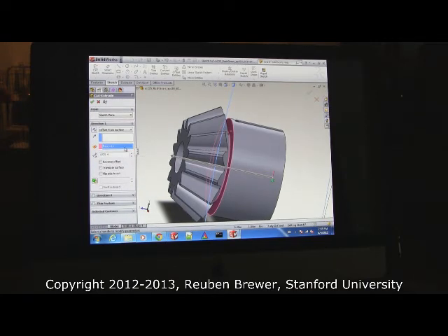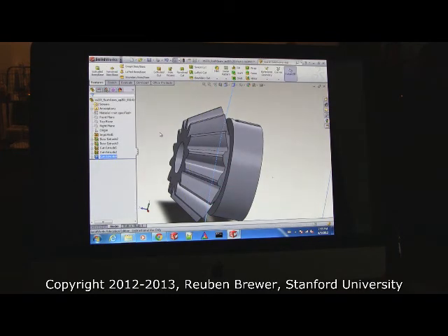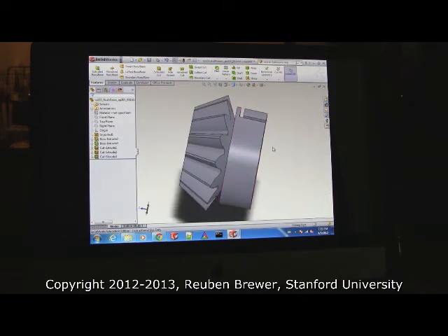So what we're doing is, this is an example of the company that makes this gear thought they would like a given hub width. And we don't like that hub width. We would like it to be smaller. The only way we can get rid of it is to cut it away. So that's why we're doing this. It's not arbitrary. So it's 8 millimeters? 8 millimeters. So now you should have a shorter, stubbier thing.